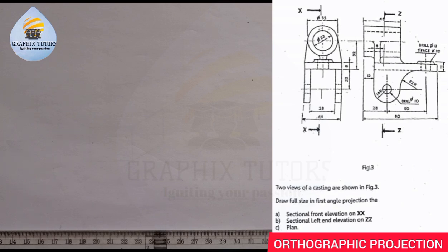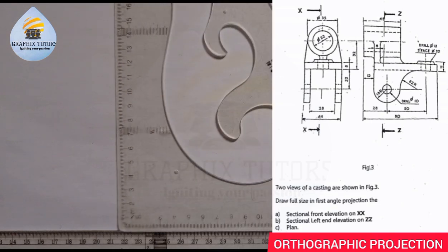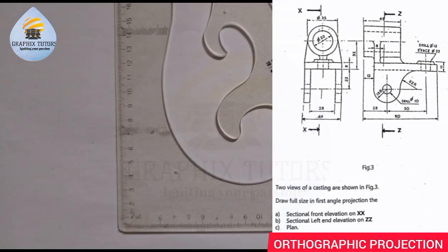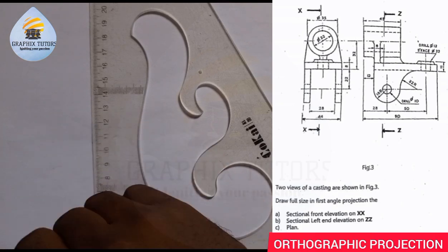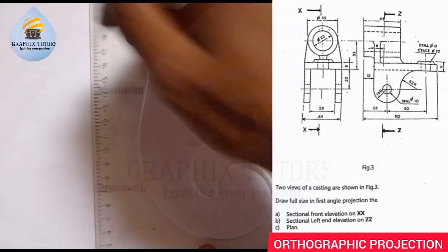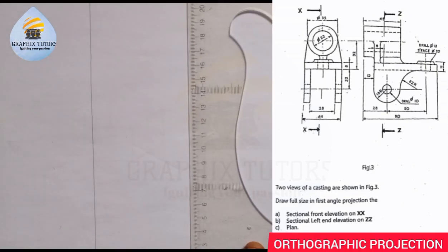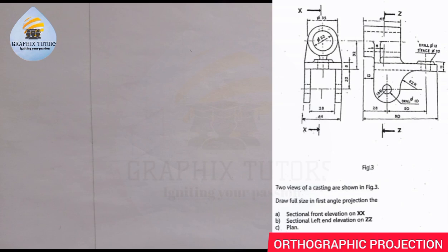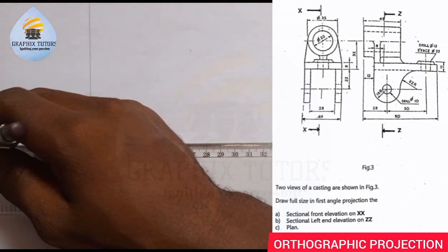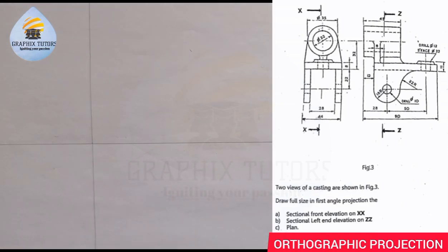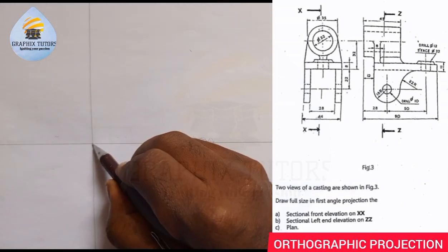The first thing you should do is to draw your quadrant, X, Y, your quadrant here. So just take your T square, place your set square on your T square, then you draw a line this way. Now take your set square, place it this way also. You draw another line this way. You can see that. So they are meeting at this point here, the pole.